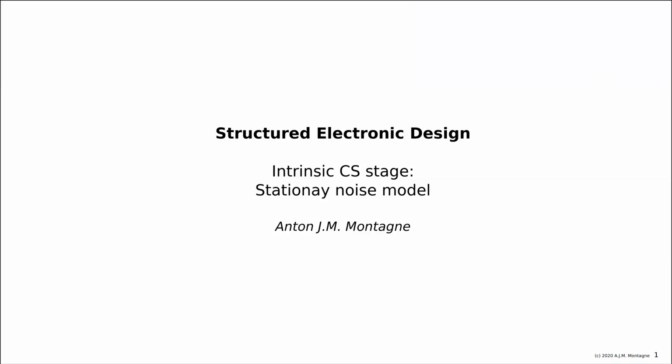Okay, the topic for today is the noise behavior of the common source stage. And I immediately see an error that I've never seen before. It is a stationary noise model that we will discuss. Stationary means that the statistical properties do not change over time. So it means that our observation time is long enough to have all possible states observed.